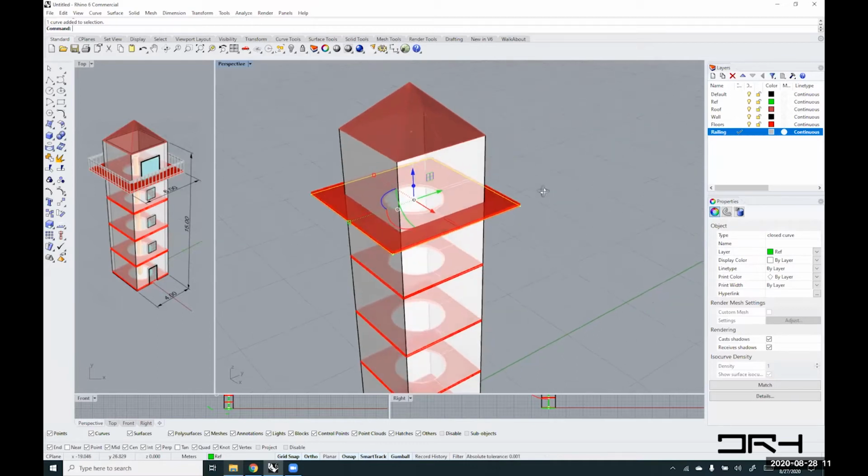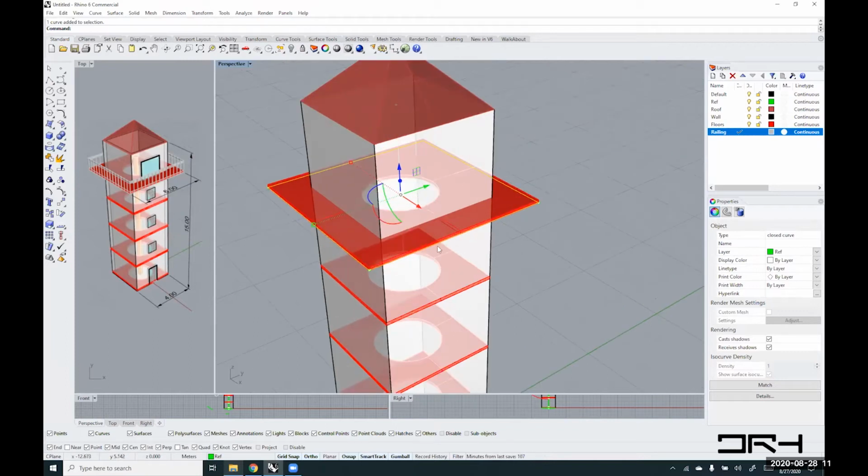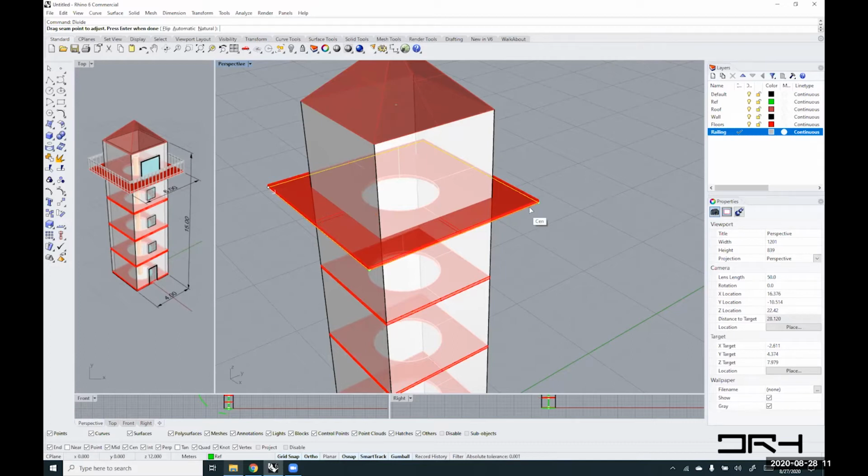There are other ways to do that, which is you can create one cylinder, one railing, and array it along a path, and you can specify the spacing. That's also another very easy way to do it. So I'll use both methods. Use the divide command, where you divide your curve, and it asks you if you want to change the seam, which is the base of your curve. In this case, I don't.